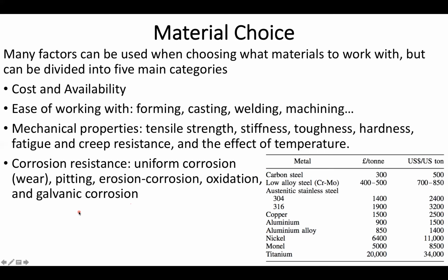And then one of the last things you have to watch out for is, again, going to be this idea of galvanic corrosion. And galvanic corrosion is often presented when you have a combination of different materials present in either a reactor or at different points along a pipe, where my two different materials have different reduction potentials. So I'm going to see corrosion at one point along my pipe, and I'm going to see buildup of oxides usually along another portion. So this can be quite a problem to watch out for.